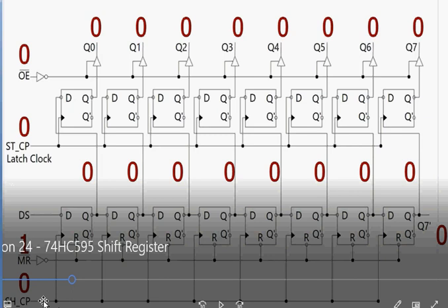When the clock is applied, and there is information present on the DS line, say 1, and we want that 1 to be output over here in Q, then the shift clock, the serial clock, should be made 1. Any data available over here, you get it over here. So at this D flip-flop end, you receive 1.